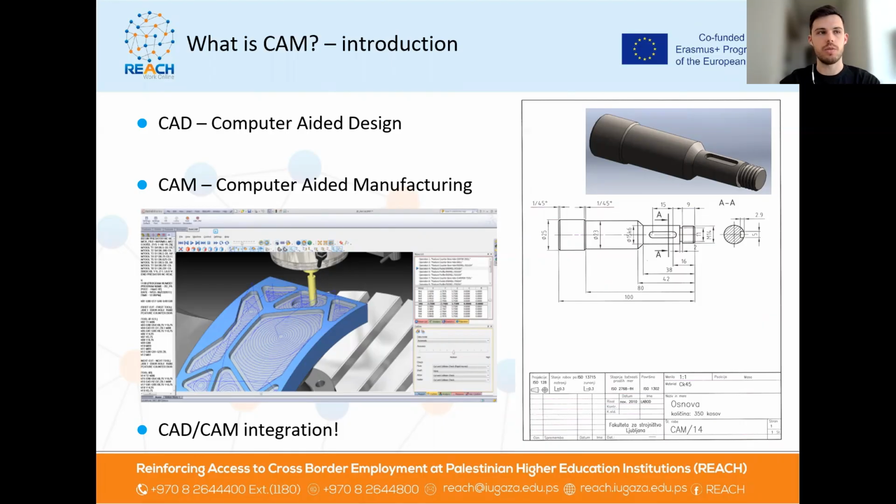You know that if you design one piece in order to have it done by machining, for example in milling, then you know that you cannot have any closed loops or any hidden features inside. Otherwise, 3D printing will be the better option. So that's why you need to always have this in mind, which operation this piece will be done by at the end, and how to then think in the design process, in this CAD process, at the end as manufacturing.